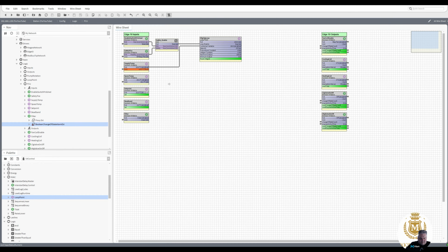Let's just put a set point in there. So that's ramping up. The control variable is 20, the set point is 21, so that is currently ramping up, which we would normally put to the heating coil, because we want to have heat at this time. So that would go to the heating coil, and then we've got the cooling coil as well.